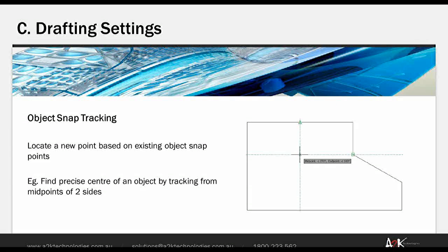If you know what those distances are, set your snaps, go to your object, hover over the object, then temporary lines will appear, and you can start typing your distances in like that. Once I've finished running through some of the different tools, I'll do a quick demo on that because it needs to be demonstrated so you can understand how it works.